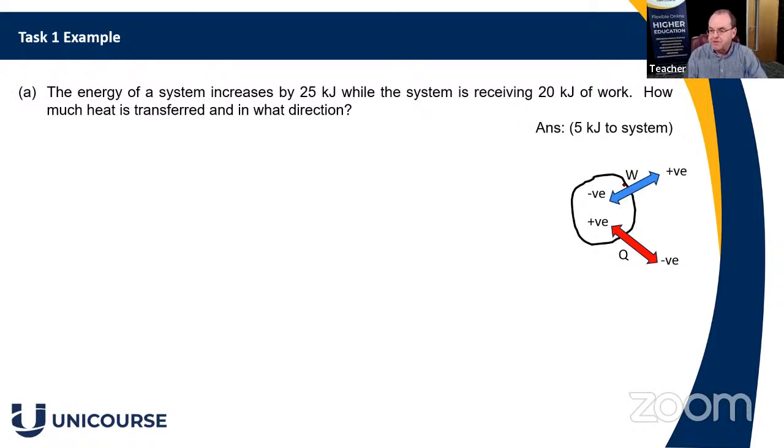Now, the way to remember this, as I said last week, is that work out is positive. Think of this as being a reciprocating engine. The work out is positive. That's useful to us, so it's good. It's positive to us in general. So that's the way to remember that. Work out is positive, so the heat out is the opposite, it is negative. It's a way of remembering the sign convention.